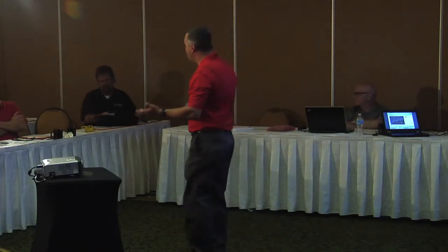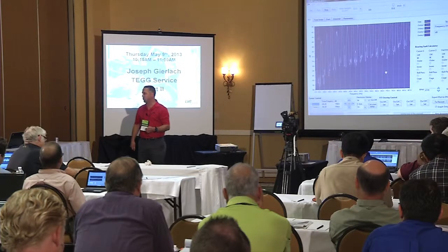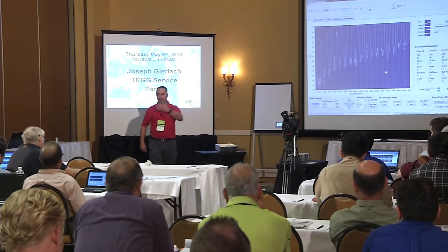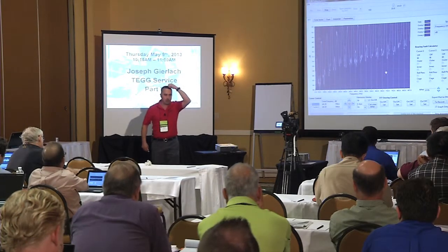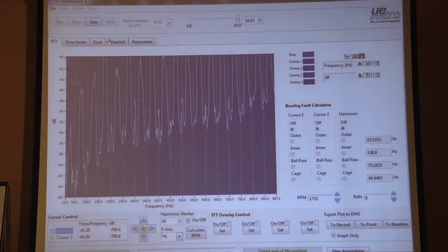I mean, transformers make noise. They emit ultrasound. That's a normal byproduct of the way it operates. So this is a case where you got to distinguish what should be there versus what shouldn't. Now, a lot of times the flag's raised, well, I hear this buzz. I'll play it again. You can hear not just the hum, but a little bit of buzz in this. And not the kind from the corona.